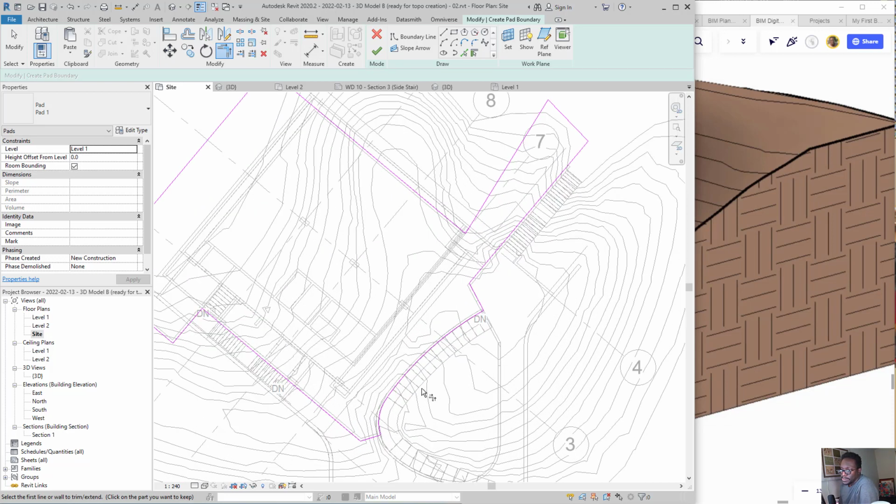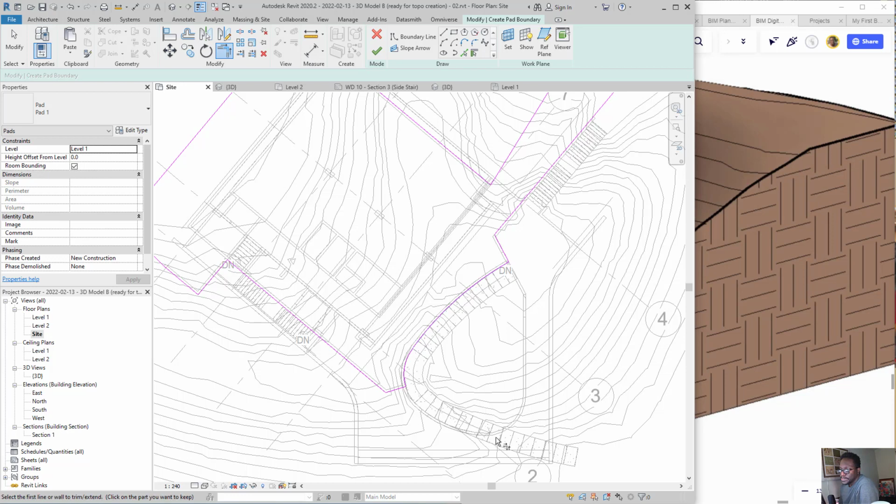And we would need the stairs to be in so that we can confirm that everything is okay with our terrain as well. So that's why it's important to actually have most of the building silhouette walls as much as you can in. We don't need to have the doors and the windows, primarily just the major structural elements like the columns and the major load bearing walls, and there's not much interior walls, so I just choose to add in these walls.